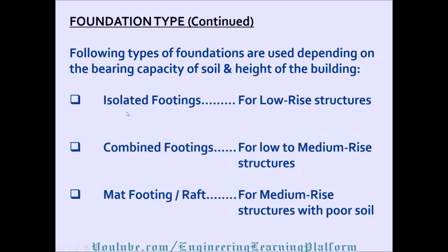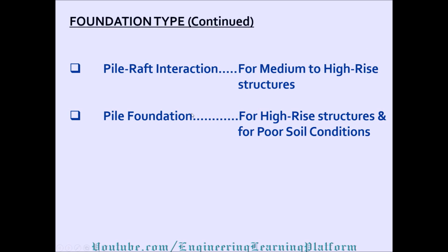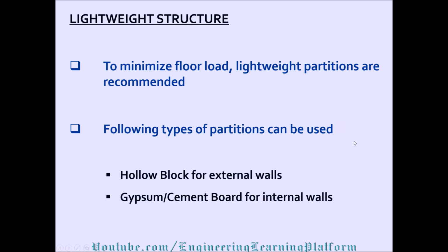The foundation can consist of isolated footings for low-rise structures, combined footing for low to medium rise structures, mat or raft footing for medium to high rise structures with poor soil. In some cases it is also appropriate for medium rise structures. Pile and raft interaction is used for medium to high rise structures, and pile foundation for high rise structures with poor soil conditions.